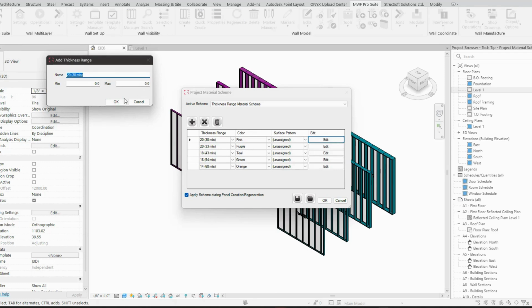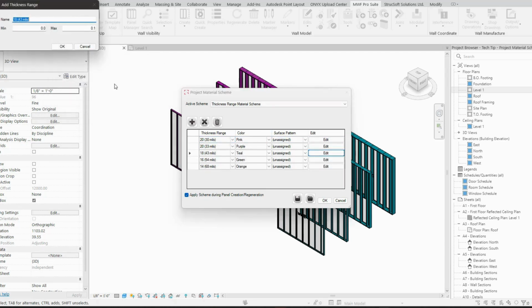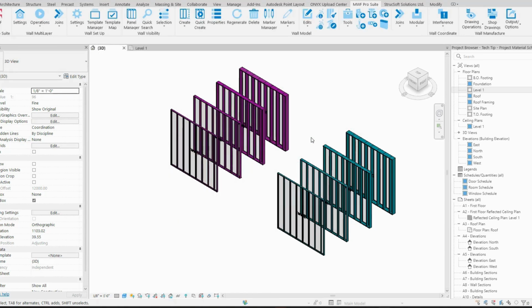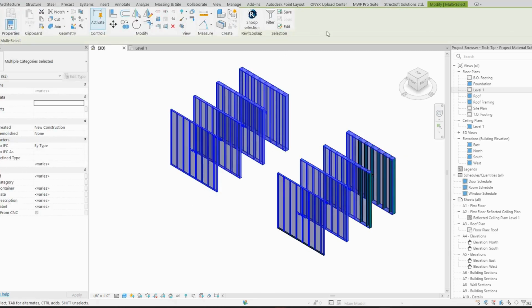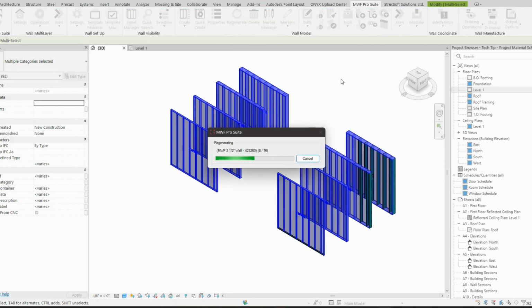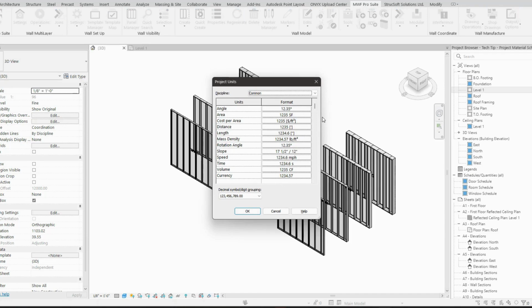So you can see 0.0 for our next option. Again, it says 0.0. And again, it's just showing us smaller values, like 0.1 in this case. And this will affect how the color is applied. So you might not notice that the color isn't actually applied to your panels because the range isn't wide enough in this case. It is seeing 0.0 and there's no difference between each option. So I'll go to regenerate the panels. And you'll notice this time there are no colors applied because, like I said before, it doesn't find a difference between the ranges because the level of precision isn't high enough.